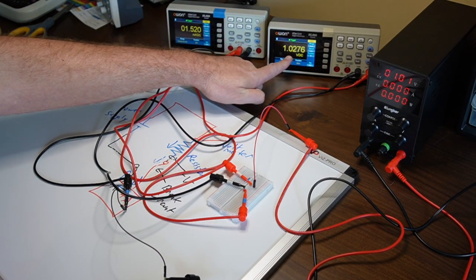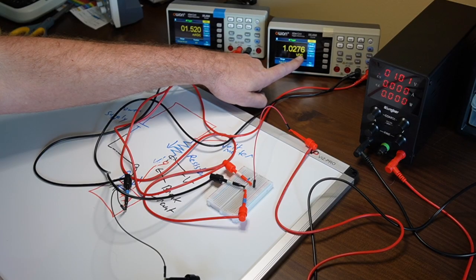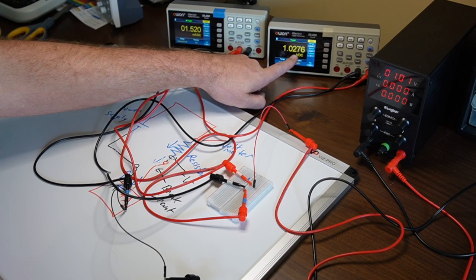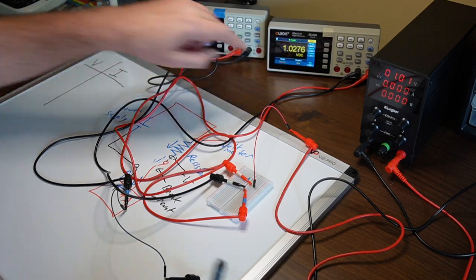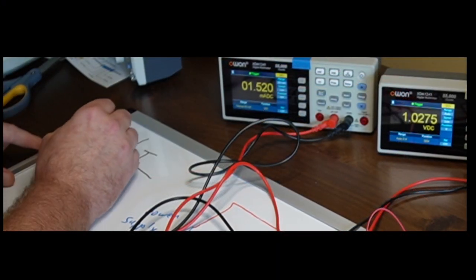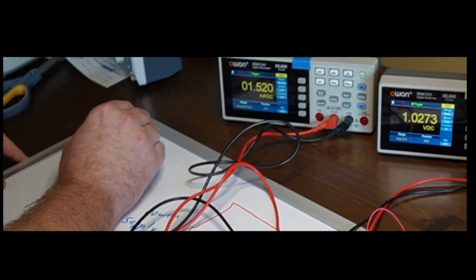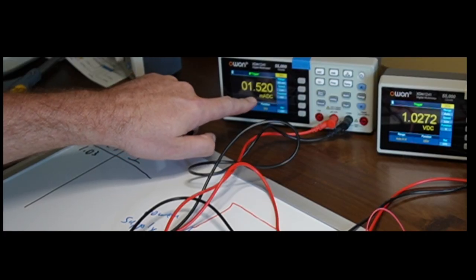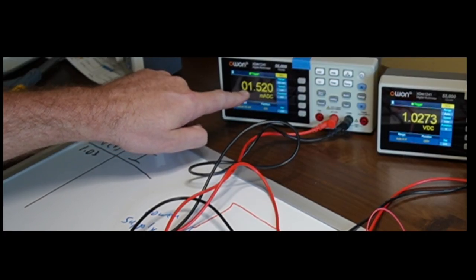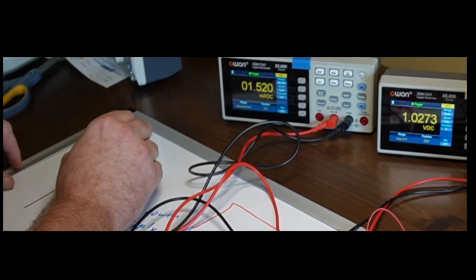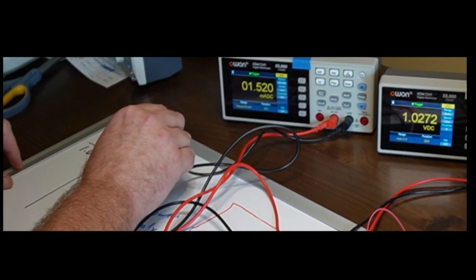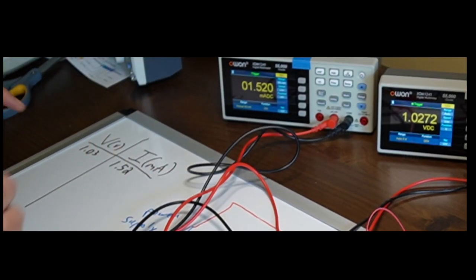And so here's our voltage multimeter value. It's 1.0276. Now I'm not going to go to that many decimal places, so I'll go to 2 decimal places, so that'll be 1.03 volts. So my first measurement, I have 1.03 volts as the measurement there. So we're going to measure here in volts. And then here's my current. Now the current is in milliamps DC, and it says 1.52 milliamps DC. So 1.52. And then I'm going to put that unit as milliamps. Now when I do my analysis, I have to make sure that I understand that I'm using something less than 1 amp. I'm using milliamps, or 1,000th of an amp, when I look at that value.